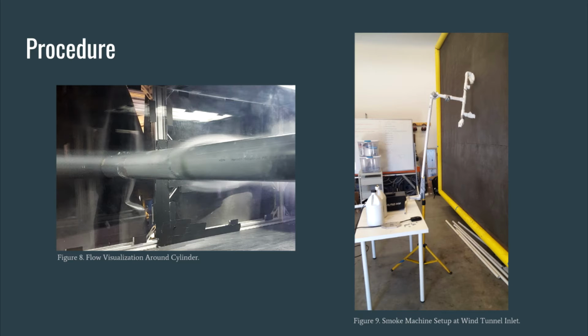The wind tunnel was then set to 100 RPM and started up per the safe working procedure. A settling period of approximately 15 seconds was allowed prior to recording any data. Once this settling period was complete, pressure readings were collected.